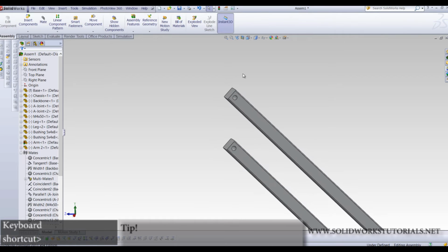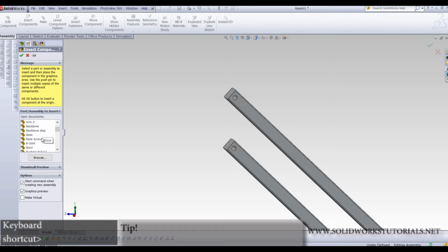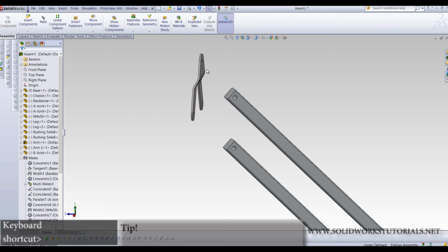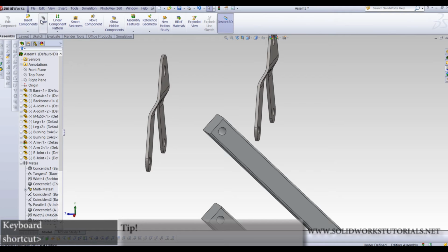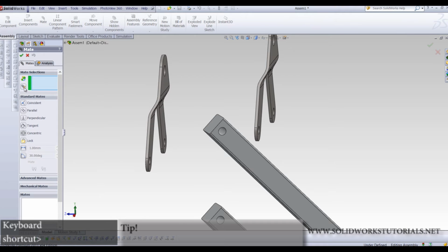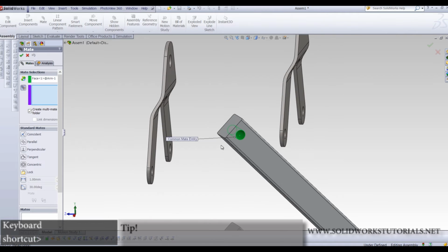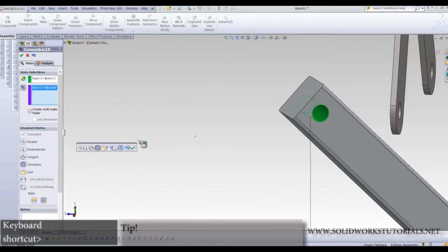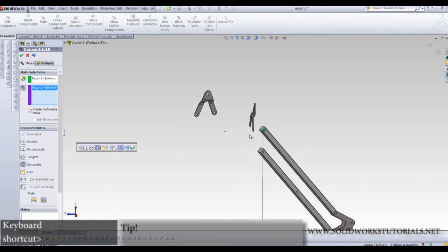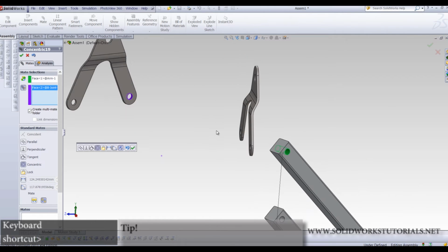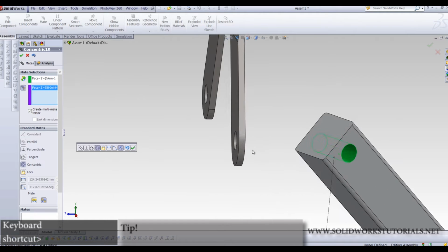Now we're gonna add the B joints to the end. So go find them first. The B joints. How many of them do we need? 2, right? Very good. For the sake of the argument, I'm gonna use the multi-mode mate again, because we're gonna have common reference here and 2 different ones there. That's the first one. And if that's the one, that should be it.